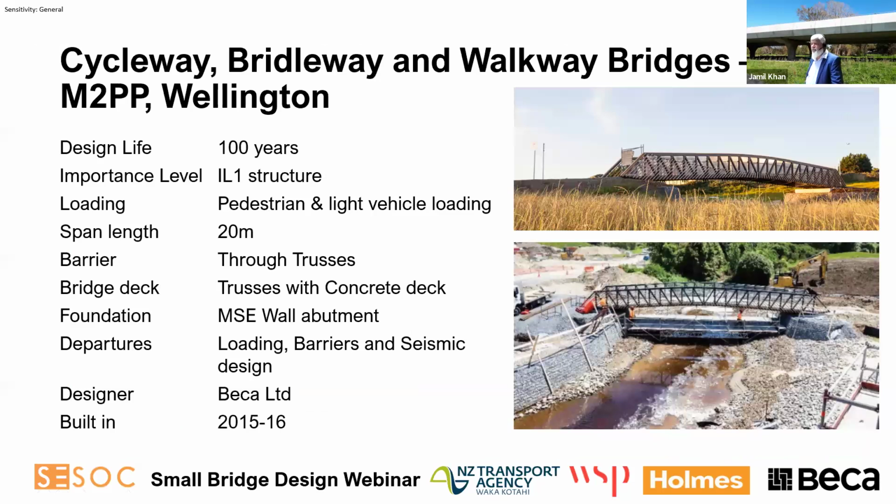The next type of bridges we're taking is the cycleway bridges, cycle, bridleway and walkway paths. This example is from the Mackays to Peka Peka Expressway, where we have three similar types of bridges. The bridges are used for pedestrians, cyclists, and carrying horse and rider. Again, the importance level was 1, and design life is 100 years.